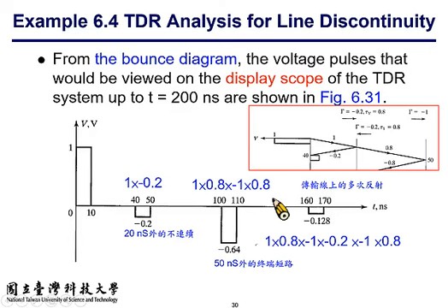And using the Gaussian diagram, you can continue with the transmission part at the interface based on the calculation of the transmission coefficient, which is 0.8 in this case. You have a signal of 0.8 going to the very right end of the transmission line, which is terminated with a short, so the reflection coefficient is minus 1 here. So the reflected signal is minus 0.8. All right? And now, what happens here? Some of the signal gets transmitted, but some gets reflected. How about the transmitted part?